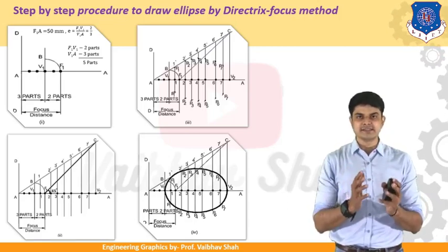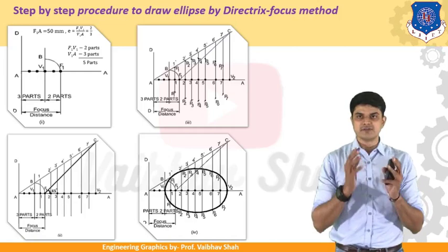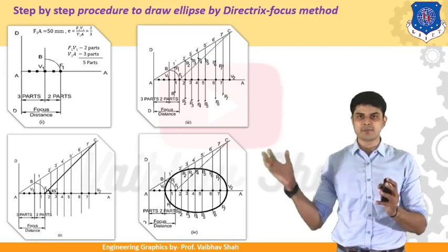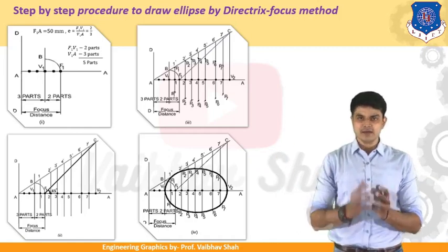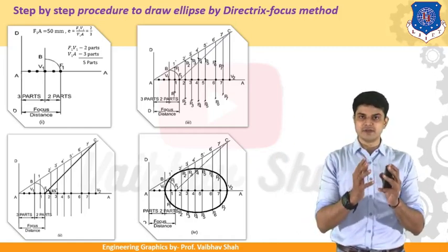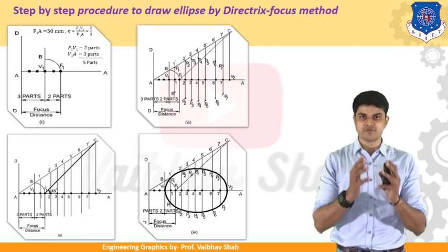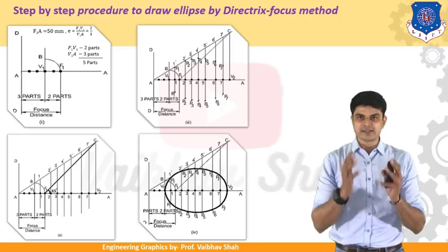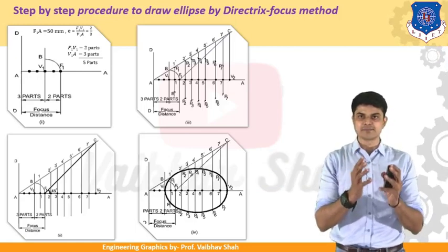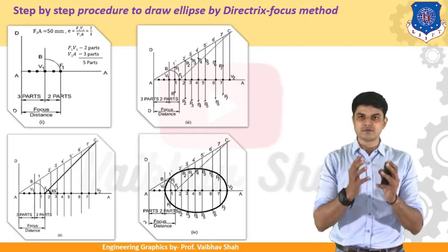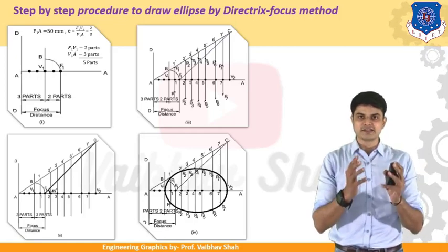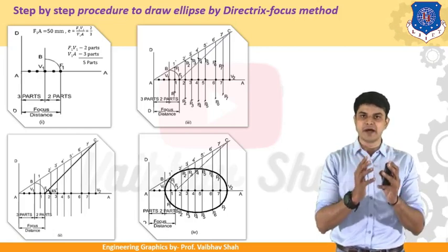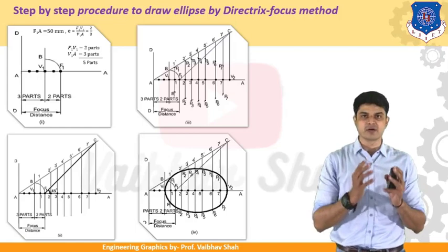Now let us see the second figure just below that figure. In it, you need to draw one line starting from your point A, passing through your point B like this. This will be your inclined line. Thereafter, you should construct another line at 45 degrees starting from your focal point F1, as you can see in my second figure. These two lines will intersect at a certain point, and from that point you should draw one vertical line. This vertical line intersects the horizontal line somewhere, and that point is your V2 point, the second vertex point of your ellipse.